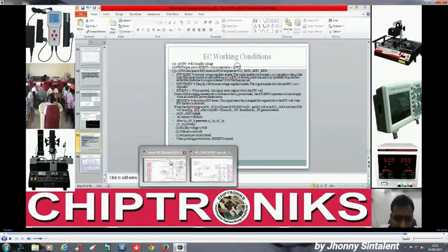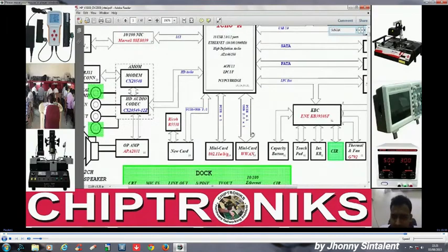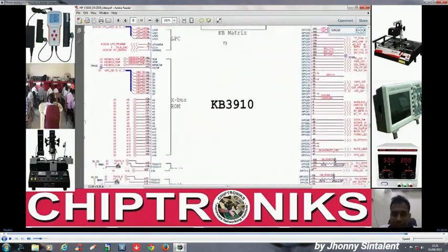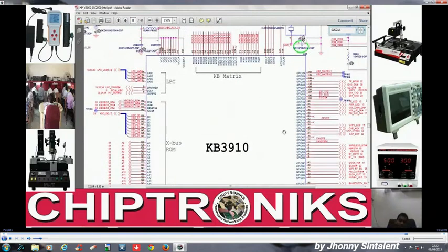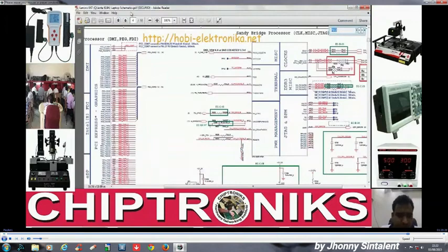And as I always say, we go to the EC of the circuit, and the EC is on page number 31, and here as a basic thumb rule, as I've always said, any microcontroller requires supply, reset and clock. So these three things are mandatory, and here we have noted +3V PCU is the EC standby voltage, reset is EC reset. We go to page number 40.